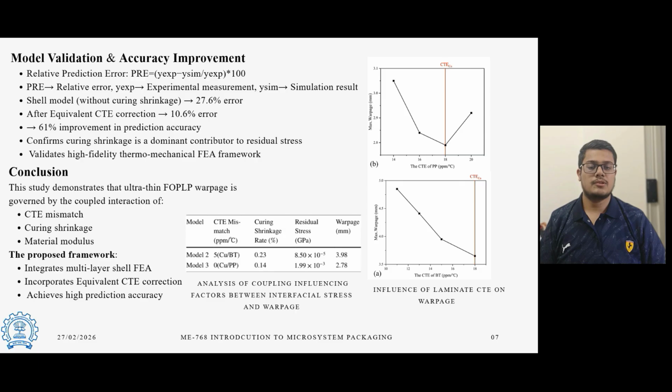So overall, the paper demonstrates that ultra-thin fan-out panel-level packaging warpage is governed by the coupled interaction of CTE mismatch, curing shrinkage, and material modulus. The proposed framework, combining multi-layer shell modeling and equivalent CTE correction, provides both higher accuracy and practical design guidance for low-warpage substrate design.